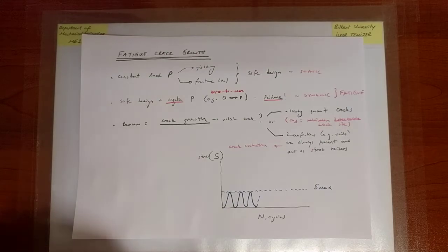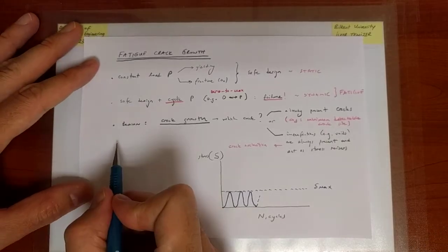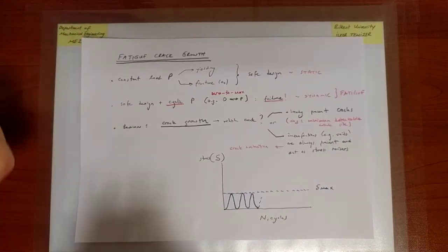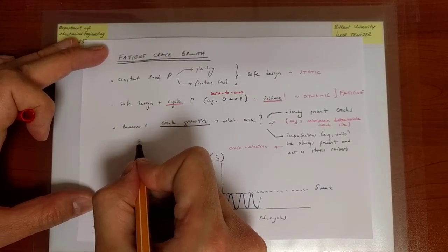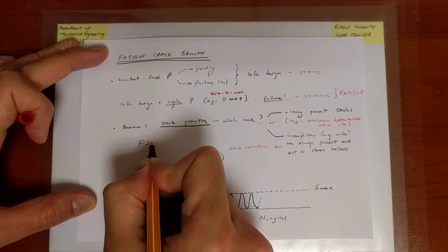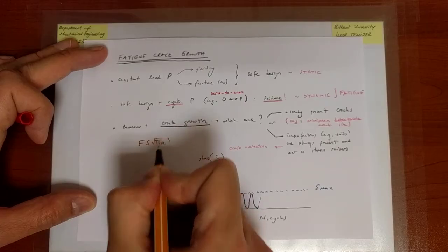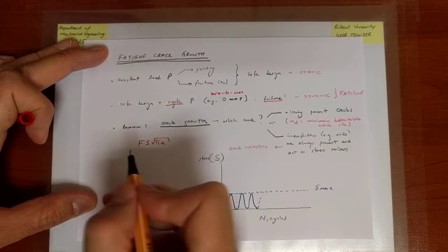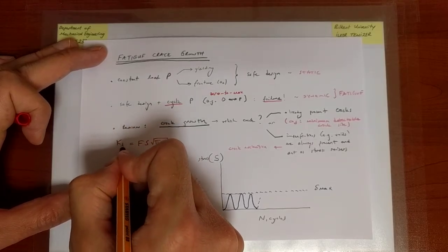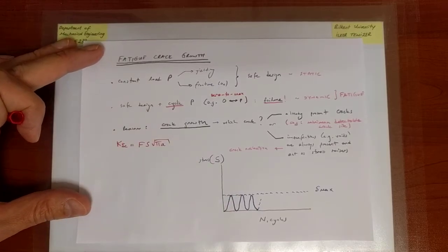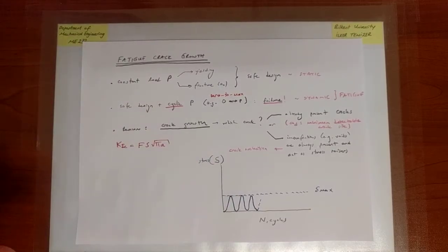So now we have a fracture criterion, first of all, and I'd like to write that over here. We have a fracture criterion that says that if I write the value of K1, which is the form factor times a load, multiplying root pi a, and omitting the safety factor, if this is equal to the fracture toughness, and I'm assuming mode 1, then fracture will occur.